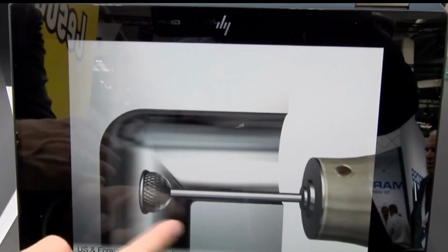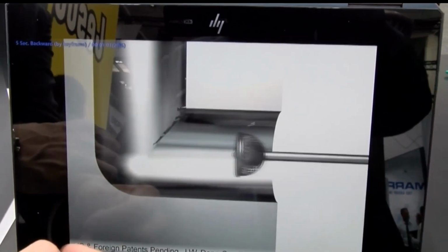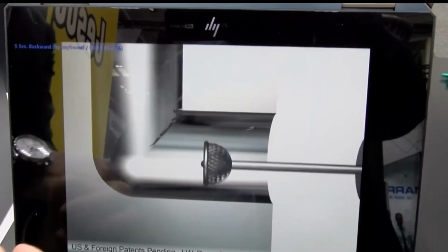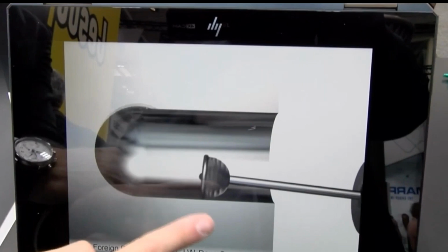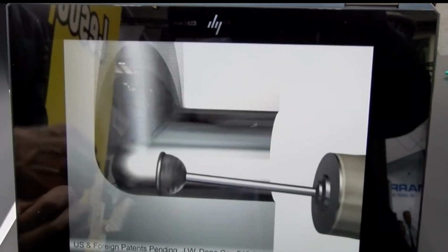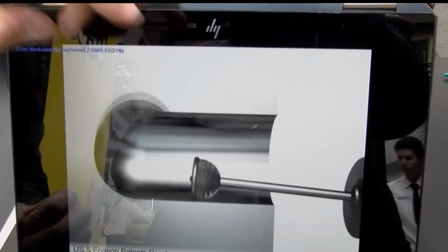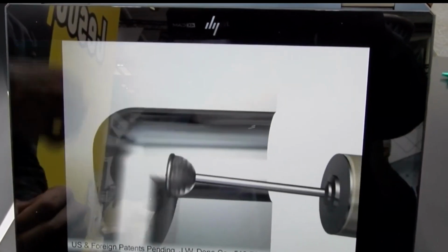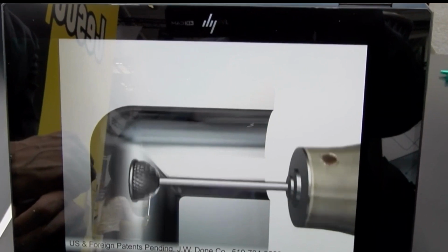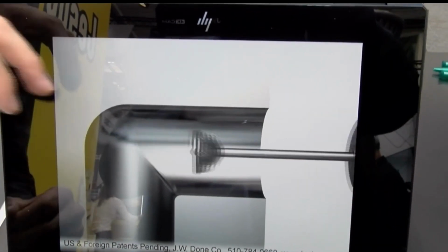Now, as we mentioned earlier, in addition to this protective ring, we've got the flexible shaft. So in this CNC setting, we're actually preloading the tool against the wall and bending that flexible shaft. So now we're developing this potential cutting pressure. And as soon as the tool reaches the edge, the disc moves past the edge, and now the carbide begins to deburr. In this case, it's an elbow.